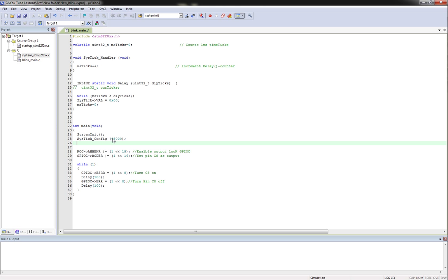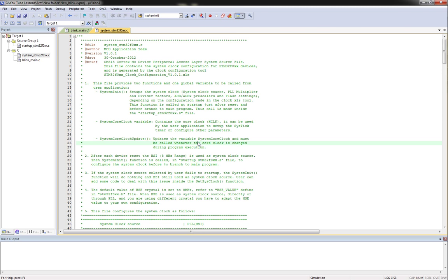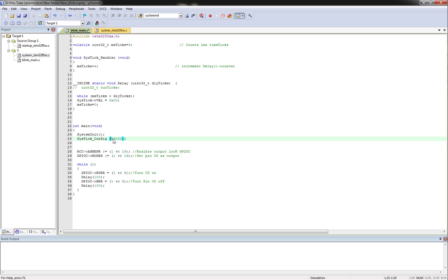I've copied this code from another project. We've got to change this number, since we chose a 16 megahertz clock, if you remember from up here. This number is what sets how fast it's going to go. It's a 24-bit down counter, and if you configure its IRQ, it'll generate periodic interrupts. And that's basically what we want.